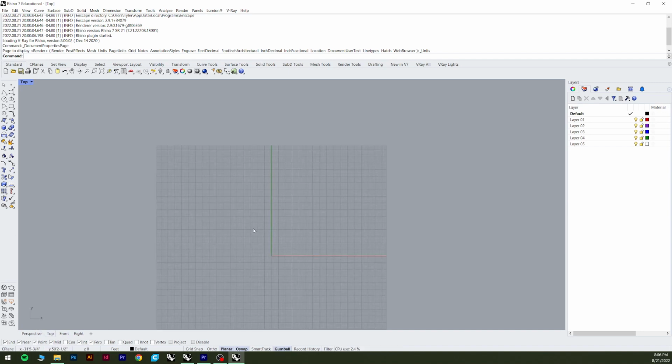since it's not 3D, you can't orbit, you can only pan. So I'm just holding my right mouse button and dragging the mouse, and then I'm able to pan up and down and in any direction. Whereas in perspective, I'm able to do the same thing, but it's an orbit. And then to do pan and only pan, you would hold shift and then right mouse button at the same time.